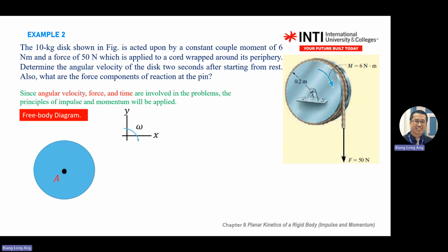So we go back, label A, radius, forces, mass. Okay. So again, as I mentioned earlier, as you go deeper and deeper, you will forget capital omega. Don't forget. This will be the careless mistake when it comes to chapter 8 questions. You can do all the moment of inertia, but you'll forget there is a weight component in the free body diagram.